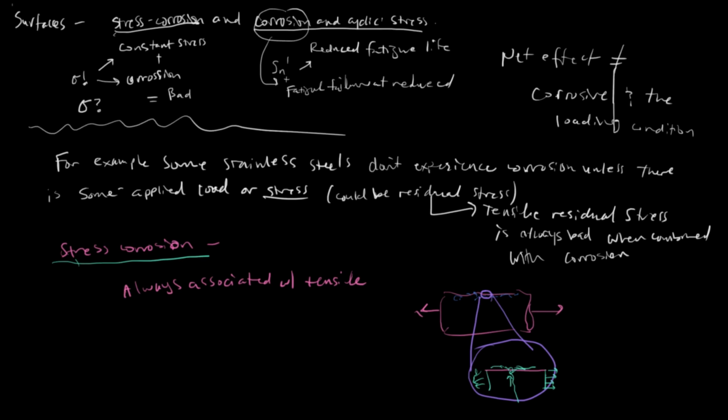And we said in the last lecture that corrosion is a mechanism that's either chemical or electrochemical, and often it involves metal ions leaving the surface. For aluminums, that'll react with oxygen to form an oxide layer, but for some iron materials, this results in flaking of the material, which flakes off in the form of iron oxide or rust.